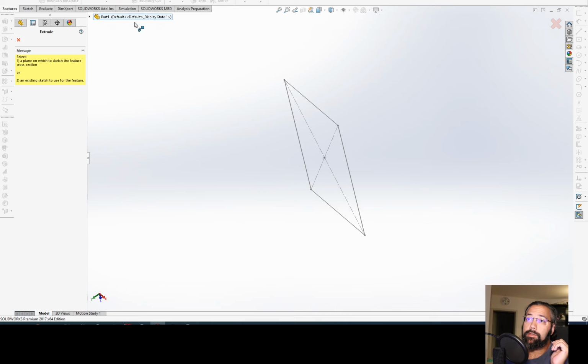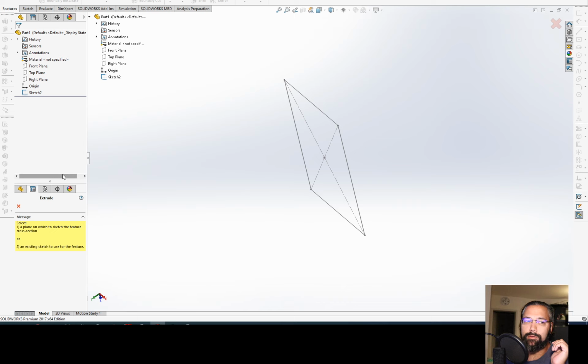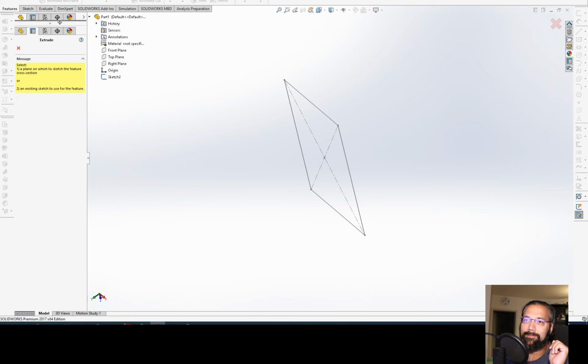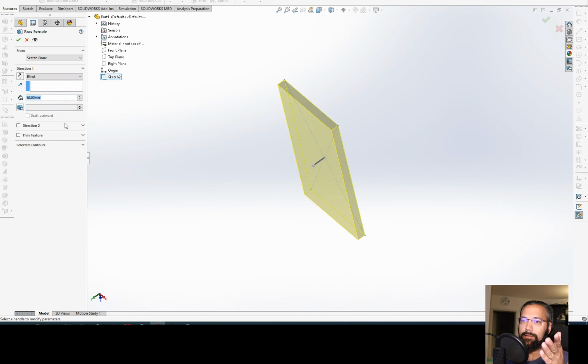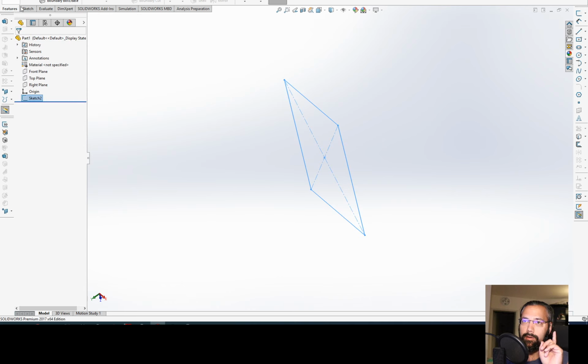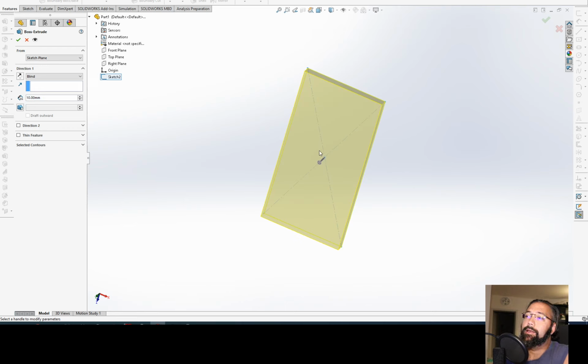Then you can open this little thing. This opens the tree that we just had. Bet you never knew this. You have this thing here, and if it's all the way here, you can't really see it, so you have to know it's there. Bam! You click this thing, you can pick it. So if I don't select anything, then you click extrude, you can click here, and then it takes the sketch and it becomes our volume. So from a 2D area, we are becoming a volume.